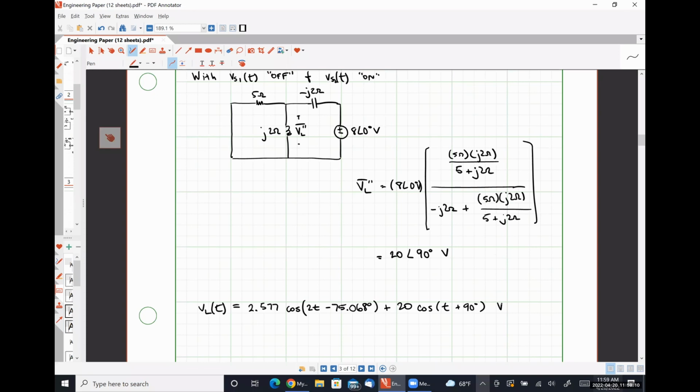So if we are taking the voltage drop over any of our elements here and we are experiencing oscillations at two different frequencies, we should expect two different terms in our result, one for each of the frequencies of oscillation. Okay, so you're 100% right. When we have a multi-frequency circuit, we can do all of our analysis in the frequency domain, but we have to break it down into an analysis at each excitation frequency, convert our results back into the time domain, and then add them together. We cannot add them together in the frequency domain and convert to time. We will get an erroneous result.